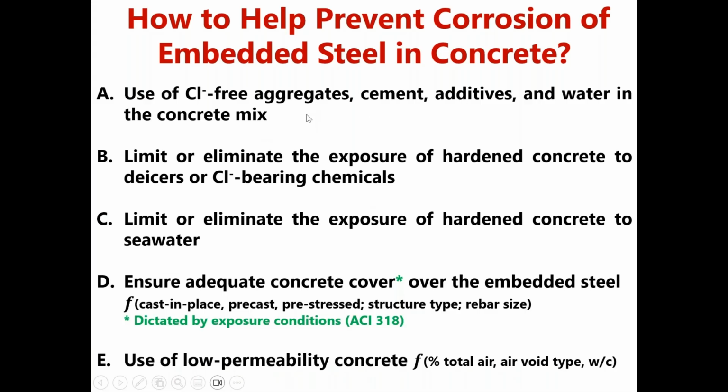So just a quick wrap up here about how to protect embedded steel from corroding. If you can use chloride-free aggregates, cement additives, and water in the concrete mix, that will help. If you can eliminate or limit the exposure of your hardened concrete to de-icing salts or any chloride-bearing chemicals, that would be good. If you could limit the exposure of the hardened concrete to seawater or seawater spray, that would be good.